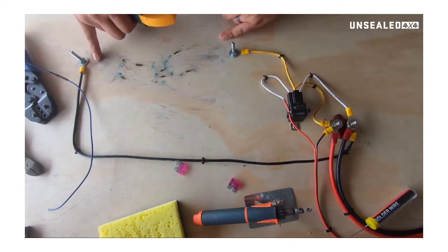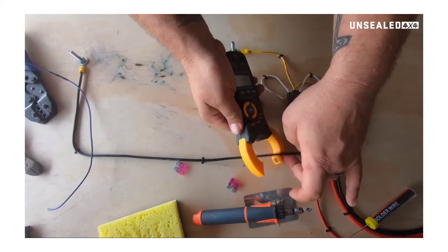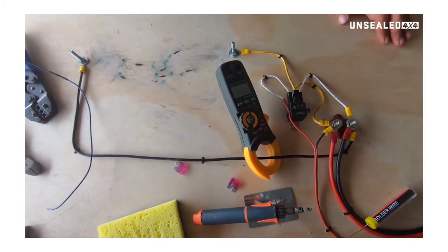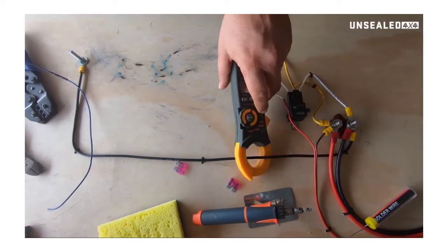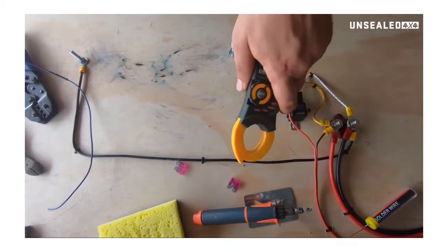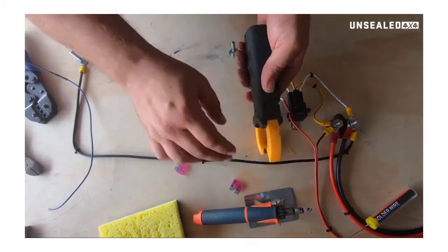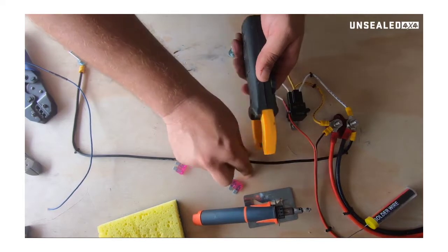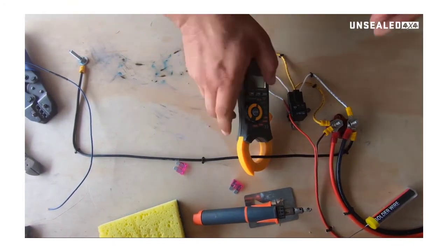So we're connected already here. You've got your light over in the background there. And then all we've got to do is put the clamp meter around that wire. And it will then tell us how many amps we're drawing through that wire. It won't work if you stick it on top, or underneath, or if you hold it around. It has to be between the jaws, inside the jaws. Once it's there, it'll give you a really good reading of that.